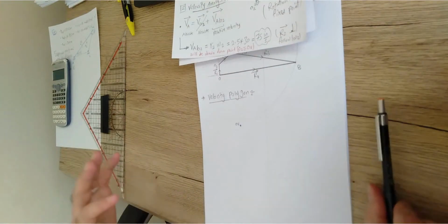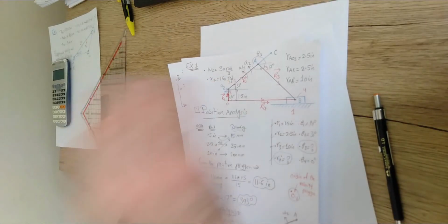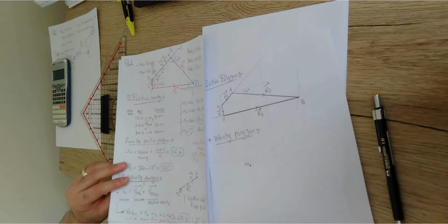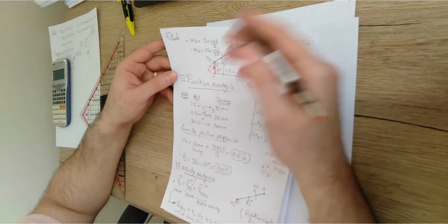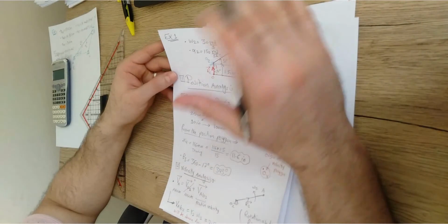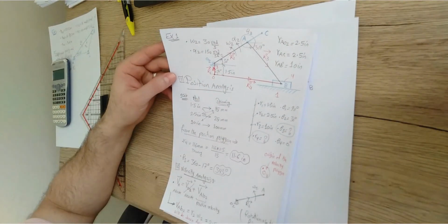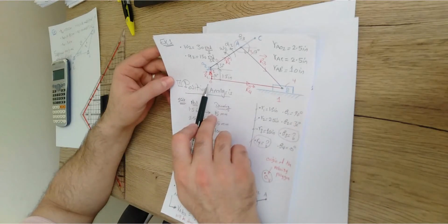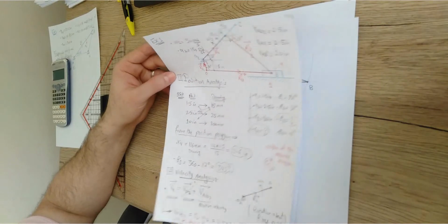Point OV is the point where any point within the mechanism with zero velocity should be located. It should be coincident to this point. So which points within the mechanism are you pretty sure have zero velocity? These points are point O2 and O. All of the other three points are moving. So what does it mean?